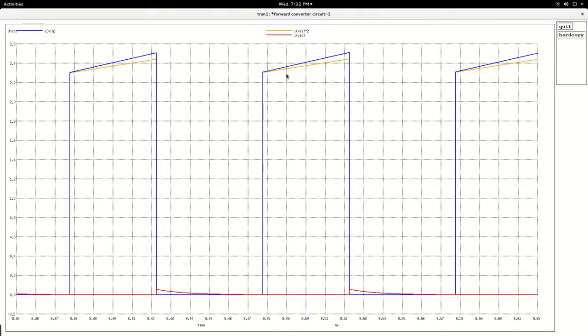Now you observe. You see the primary and the secondary are exactly the same except for the difference, which is the magnetizing part. So the primary switch current is composed of the reflected part and the magnetizing part, and the magnetizing part is an amount equivalent to this, which will come and match exactly here, and then this will start exponentially decaying.